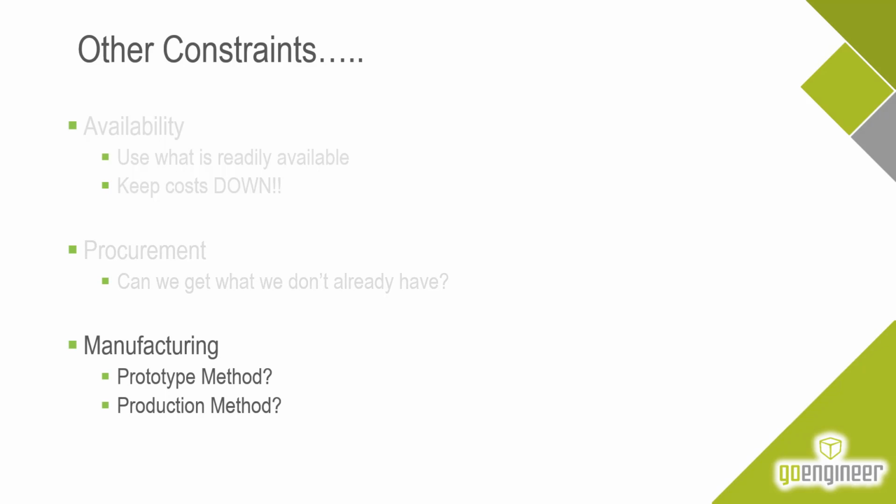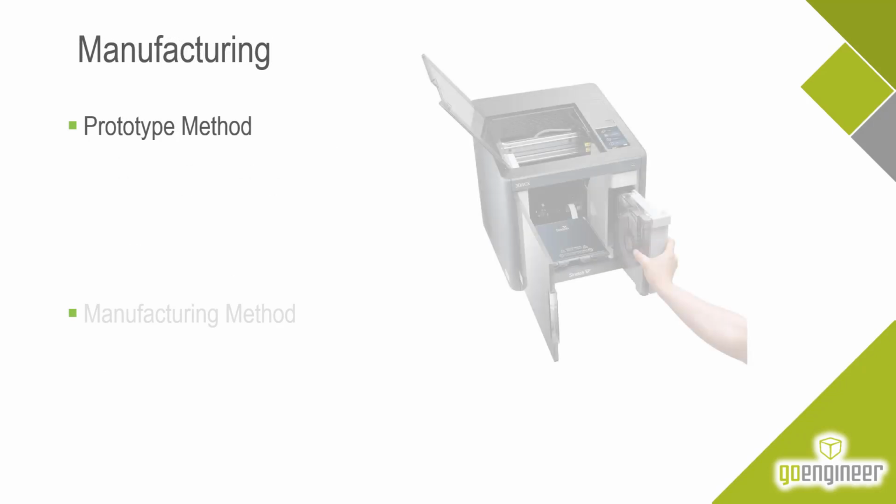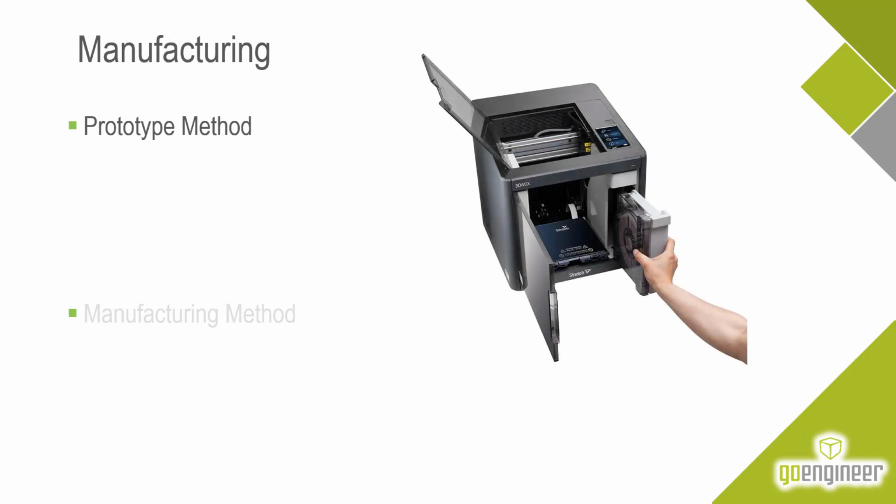But I always think manufacturing, especially prototyping. And when I'm going to go ahead and prototype something, I'm going to use my 3D printer. Now, I've had this one for about 5 years, but printers are available in pretty wide ranges. Again, from FDM to all other methods, from anywhere from $500 for pretty good ones, all the way up to $500,000 in those ranges. Now, use whatever is available to you. In this particular case, FDM or FFF, fused filament fabrication, is what I choose for most of my end-use goods.